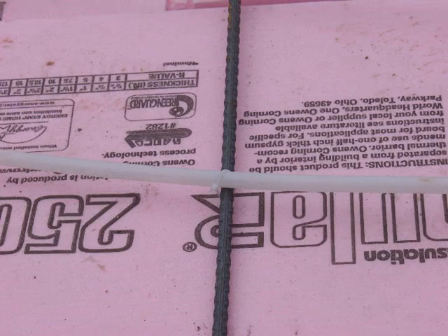To keep the tubes in place, we use just regular zip ties. And now we want to be sure when possible to keep the tubing underneath the rebar or running to the side of the rebar. Now here we're crossing perpendicular, so there's not much choice here. We have to go on top. But the lower you can keep it on the rebar, the better, so that you have enough room between the top of the tubing and the top of the slab.